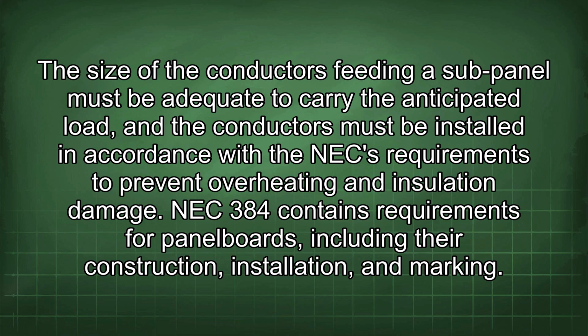The size of the conductors feeding a subpanel must be adequate to carry the anticipated load, and the conductors must be installed in accordance with the NEC requirements to prevent overheating and insulation damage. NEC 384 contains requirements for panel boards, including their construction, installation, and marking.